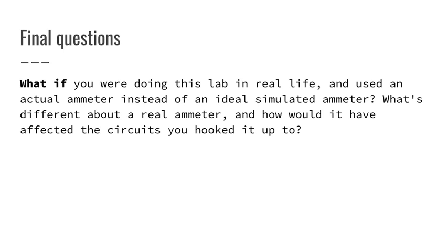Lastly, we answered a couple of questions. The first of which asked, if we were to do the lab in real life, what would be different about the ammeter compared to our simulated one? In real life, all components have some resistance. By including an ammeter, we would not be able to measure the exact current. Simply by including it in the circuit, we will change the value slightly.